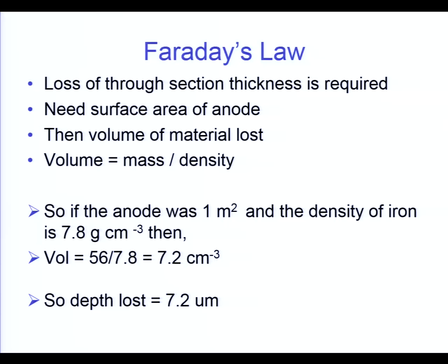But the reason why I've gone down to microns is because in reality that's the sort of rate you're dealing with. If you look up corrosion rates in millimetres per year, they're fractions of a millimetre per year, hopefully, unless there's something seriously wrong with your plant. You're right, from a scientific point of view you go for standard units, but in reality we go for things that are close to give us values that are typical of what we're going to find. So as long as you stick with like for like, you'll be all right.